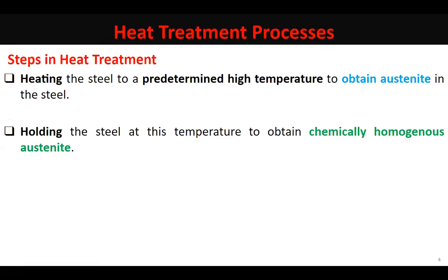And in the pearlitic structure, what did you have? You had a lamella of ferrite, and then an alternate lamella of cementite, and then an adjacent lamella of ferrite, and again an alternate lamella of cementite. It is these very regions where austenite is getting formed. But because ferrite dissolution is complete and cementite dissolution is still incomplete, in the original pearlite structure, wherever cementite lamellae were present, still some cementite, which is largely carbon, is present. So you say that when I have reached the heat treatment temperature, austenite formation has got completed.